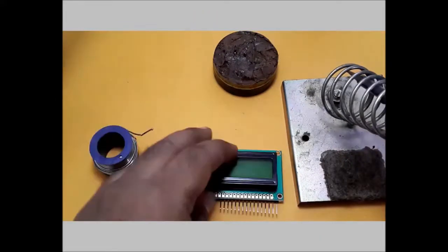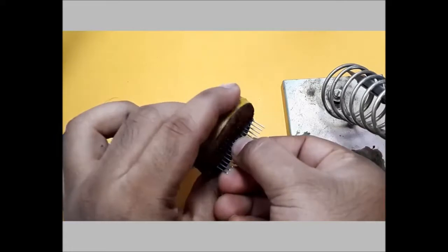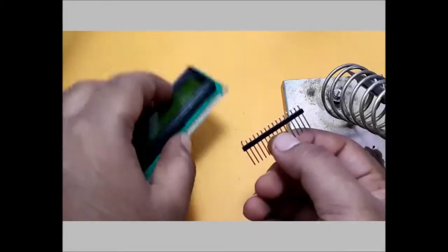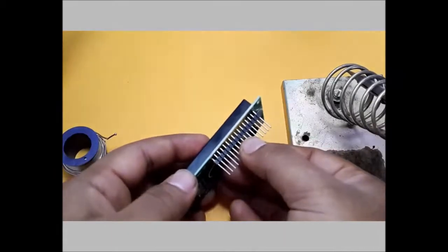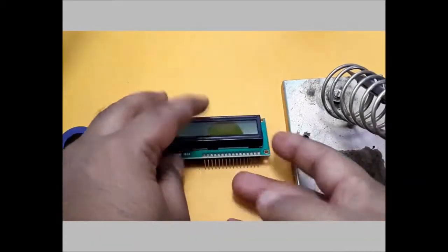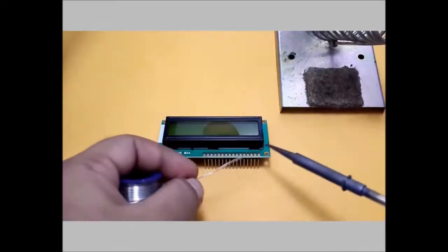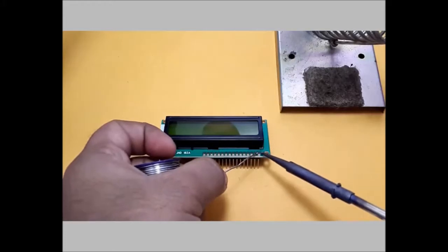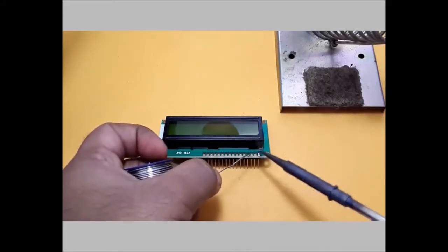First, put the external pin on the LCD as shown. Next, apply the solder paste to the tip of the external pins as shown in the video. Then, place the LCD with the external pin firmly on the flat surface as shown. Then, it will not shake while we do the soldering. Take the solder rod with little paste and touch the tip of the wire as shown. Hold it for a few seconds so that the wire melts and apply to the external pin as shown.